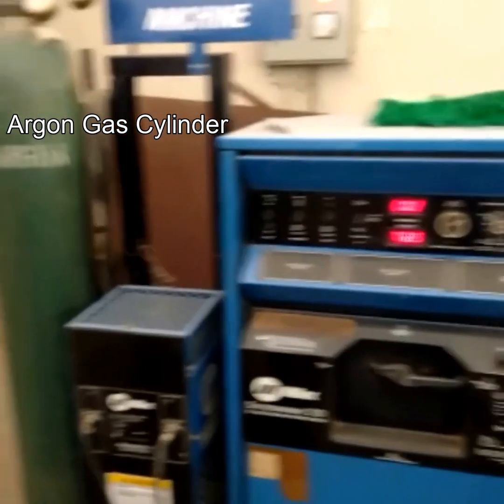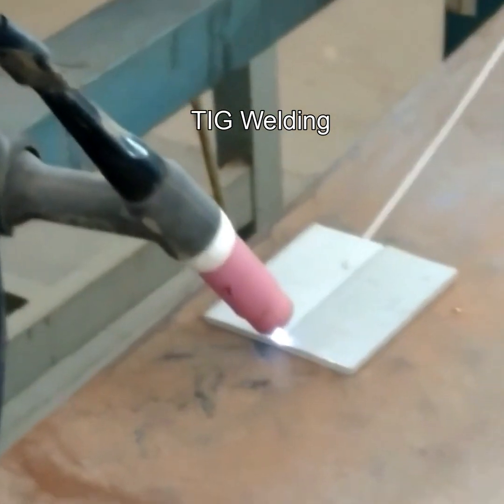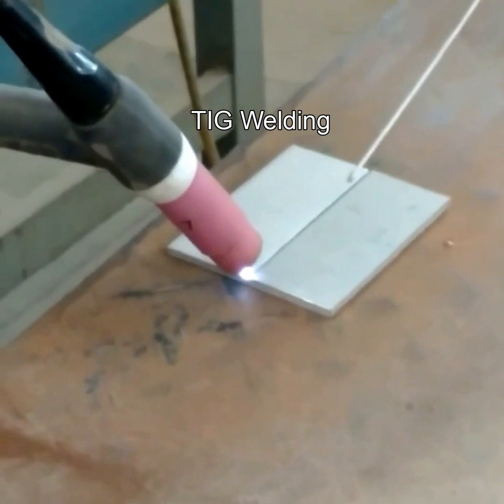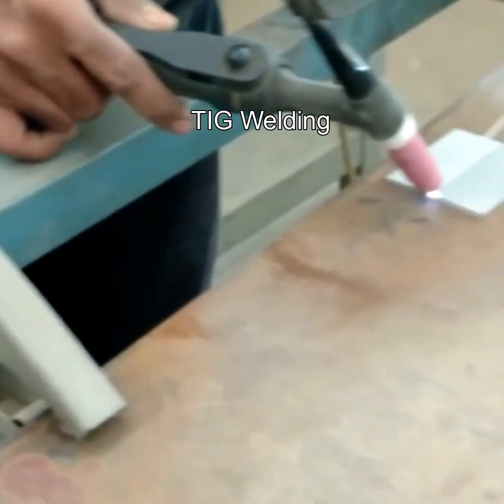TIG welding is being performed with aluminum workpieces that are going to be welded to form a butt joint. The filler material is also made of aluminum. You can see the arc over the surface of the workpieces that is used to melt the base metal and workpieces. We are performing this TIG welding using alternating current.